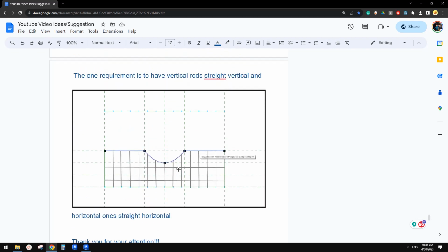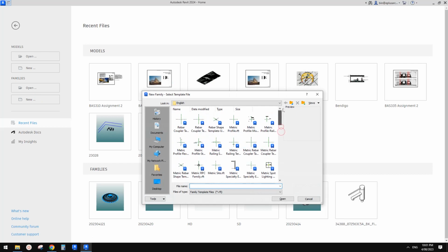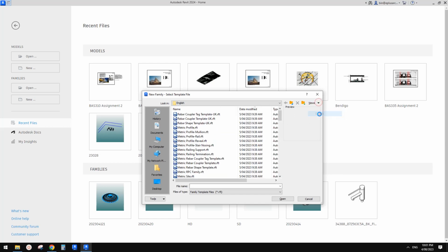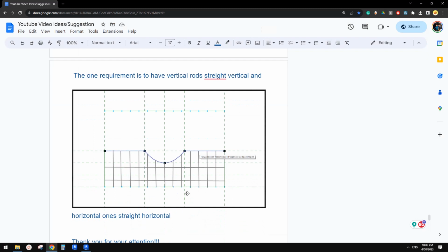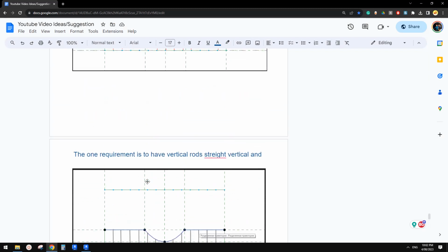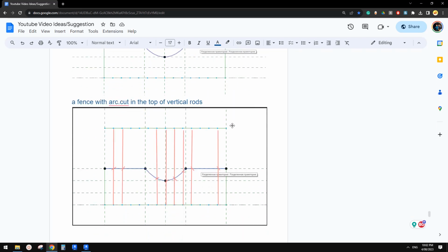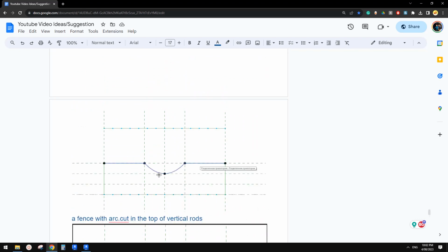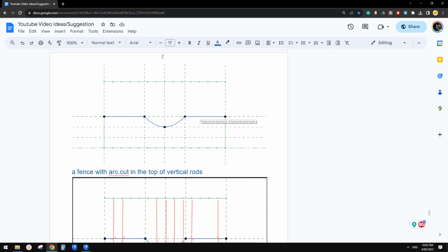So let's do it. Also today I'm going to try 24. First we need to create a generic model, adaptive. So let me change this to list. Maybe detail. Yeah, that's better. Generic model, adaptive. It looks like there are some reference plans here. When we do adaptive family, we don't really need those, and there are no adaptive points. Actually there are some reference plans.